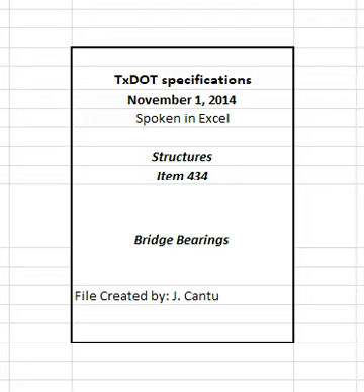bottom plate. Plain and laminated elastomeric bridge bearings are designated by hardness, durometer, size and configuration and, in the case of laminated bearings, by the thickness of the individual layers of elastomer and the size and position of any steel top plates. 1.2 High-load multi-rotational, HLMR, bearings.